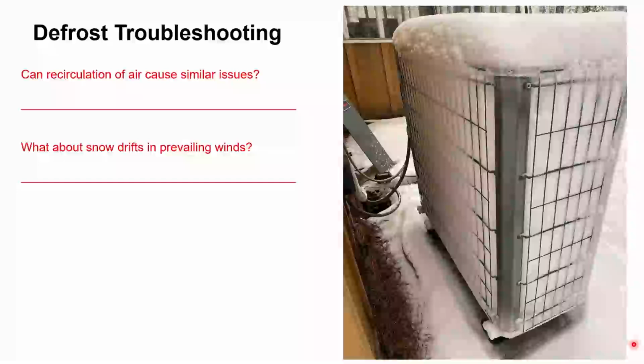So it was basically in a little bitty chamber, and we couldn't get proper air circulation. So we do need to watch our snow drifts. And they ended up building an awning over the top of this thing about 6 feet above it. Please do not put an awning on an updraft model a foot above the unit, because then you will cause recirculation issues.